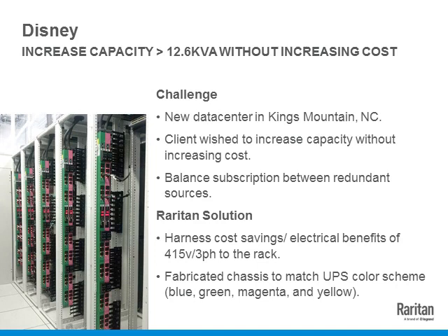They don't want people to plug the power strips into the same circuit, like the same A feed, and then oversubscribing A while the B feed is completely open, or it's undersubscribed. So they had two unique problems, and we worked with them to make sure we can provide a solution that will keep the cost down, but also provide additional capacity.